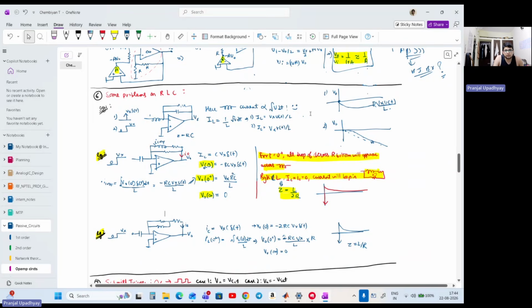So the first thing that we have already learned is that we must check whether the negative feedback is existing or not, right? Before this input came, the circuit was at DC only. At that point of time, when the circuit is at steady state, or when the input wasn't applied, negative feedback is not essentially active in the circuit, because this inductor will effectively be grounded and thus the feedback factor is zero. But the moment you apply an impulse, this feedback comes into action, right?